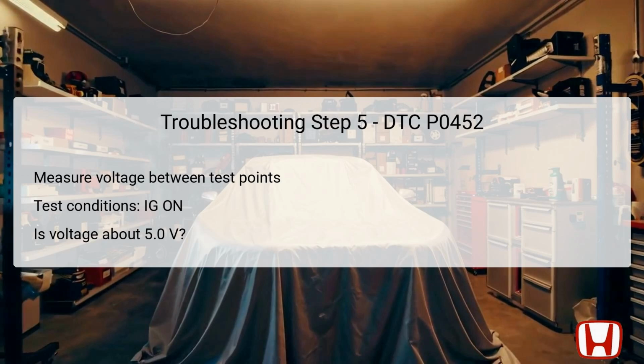If the measured voltage aligns with this expectation, it confirms that the FTP sensor is faulty and requires replacing. Conversely, if the voltage deviates from this threshold, it may point towards an open circuit or other wiring issues. This particular analysis is crucial as it helps pinpoint whether the sensor itself or supporting circuitry is at fault and guides the next steps for effective resolution.